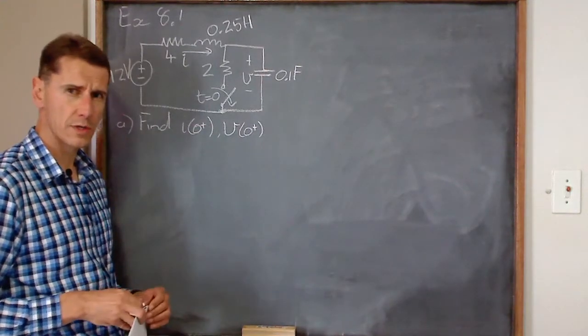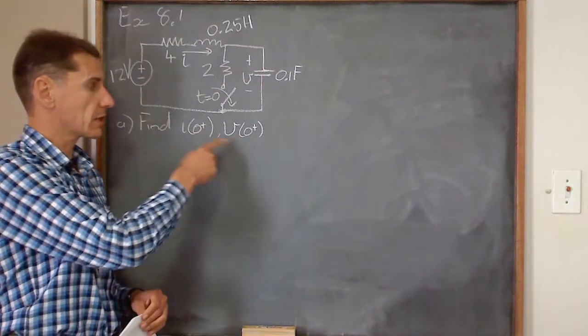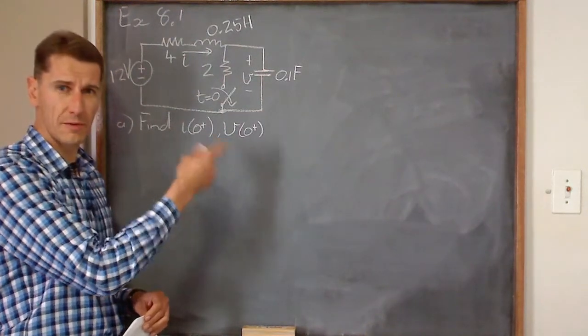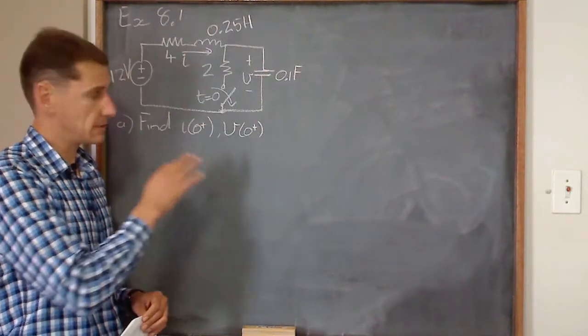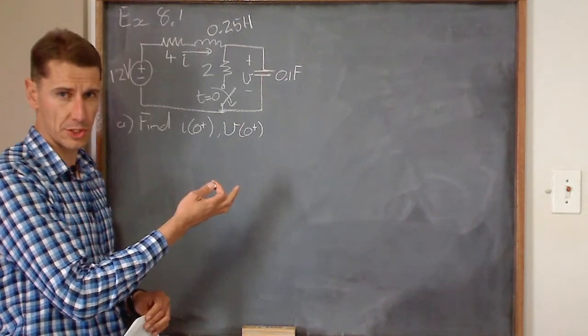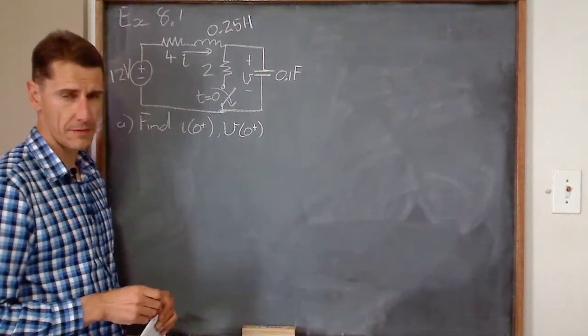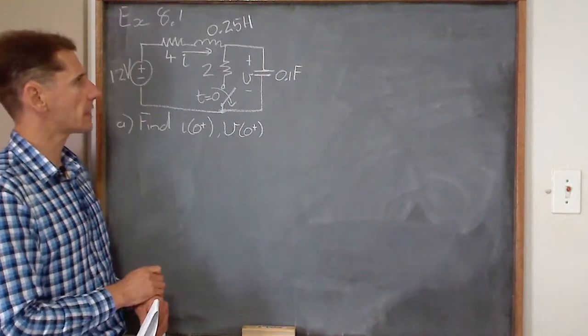So with the first order circuits, we just had to find the initial current or voltage and time infinity and the time constant. Now, there's these 2 initial conditions plus the dv/dt, the di/dt initial conditions, and there's the infinity values. So let's start. This we should be comfortable with.